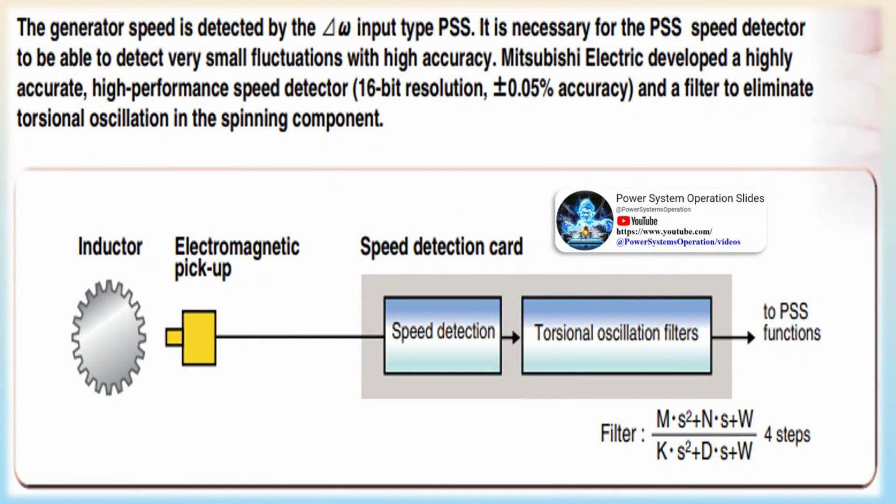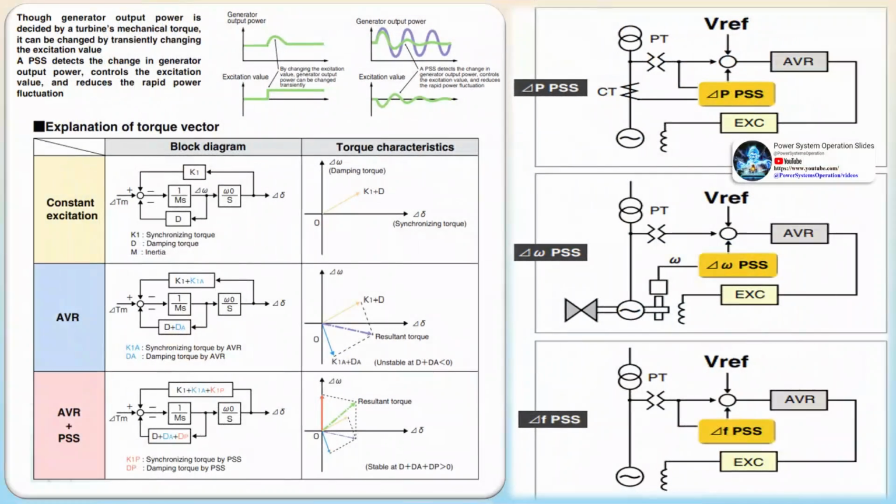A PSS does this by sending a control signal to the generator voltage regulator when such oscillations are observed. This rapidly changes the generator operation to counteract the frequency oscillations. Stability is an important part of ensuring operability of power generation systems. Large transients can cause power systems to become unstable and can eventually lead to blackouts. Power systems need to be designed to withstand large disturbances and maintain stability under changing operating conditions.